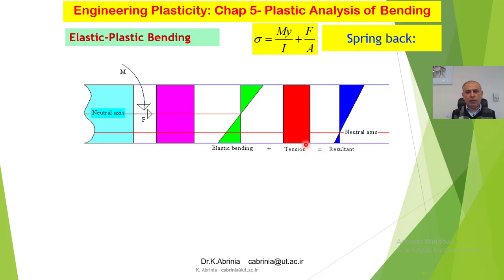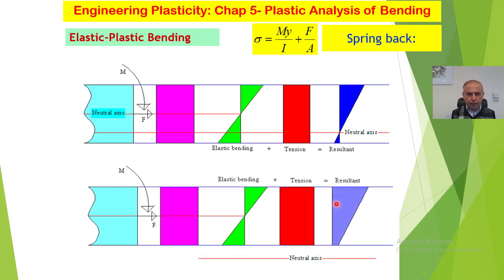We could do the same thing with compressive stresses. If this is negative all the way, compressive stresses, having a compression on the cross section, then we could move this neutral axis out of the plane that way, and all the stresses will be negative. Okay, like that. Here, obviously, I have applied a larger magnitude of tension, and so I have moved this neutral axis out, it's gone here. If you move that, the neutral axis is there.